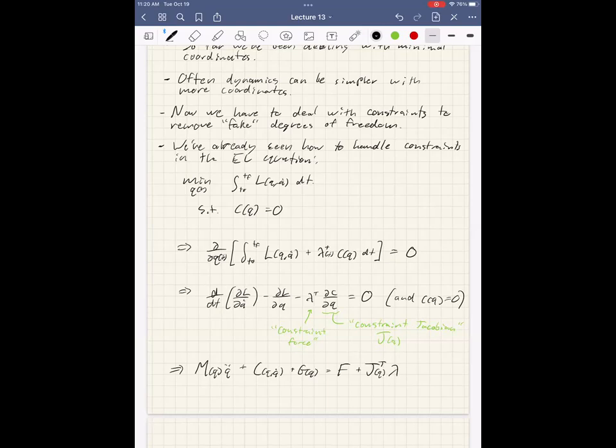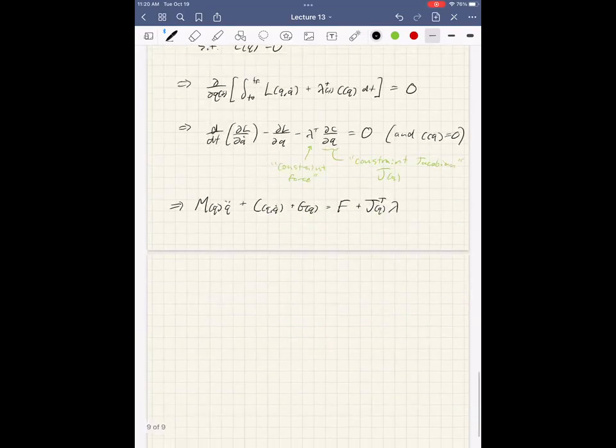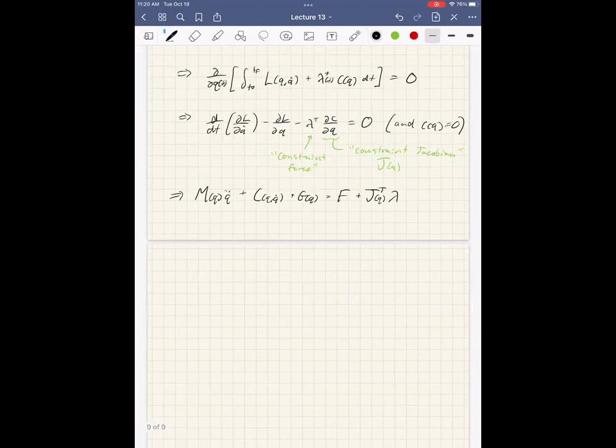So this is just like we did before with standard optimization. I set the gradient equal to 0, I get this Lagrange multiplier term, and then I have the original constraint. I have both sets of conditions. Thoughts? Yeah, so we're going to have to set up some kind of KKT system that has this and the constraint equation. And we're going to have to jointly solve that KKT system for both Q double dot and lambda, right?